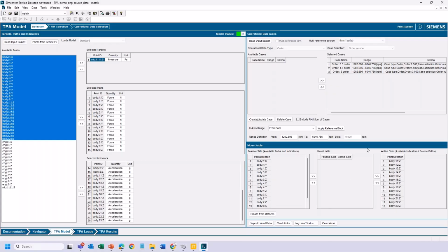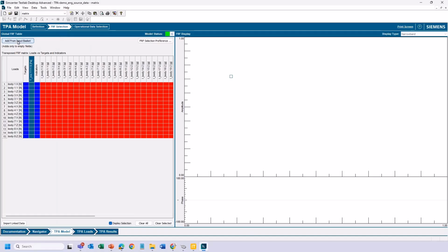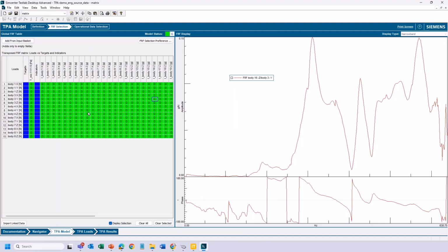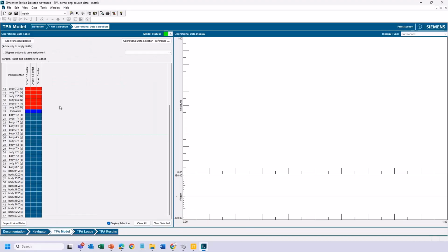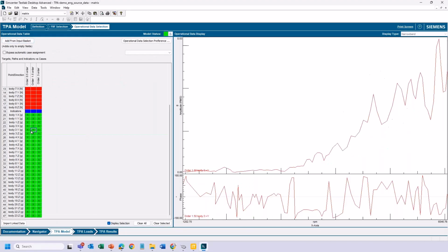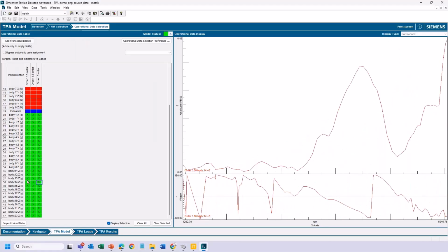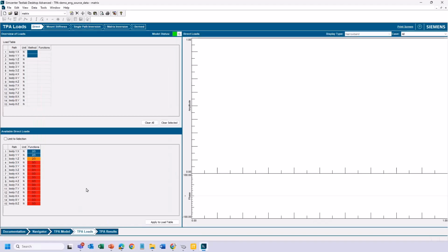We're not going to use this mount table though anymore. Now we got all the FRFs and we got just a ton more FRFs all measured cross, etc. We got a ton more operational accelerations at all these additional locations. So we've really made the measurements go up quite a bit with this matrix inversion.